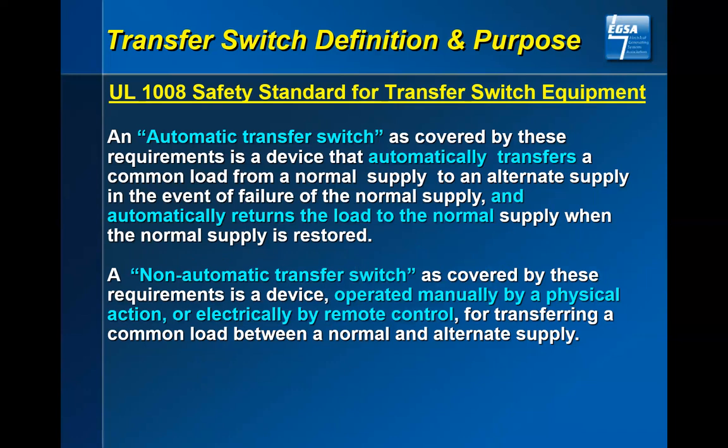We're back to Article 700 again. That automatic transfer switch is covered by these requirements. It automatically transfers and it automatically returns to normal. As I stated, it is power seeking. That is a typical automatic switch.